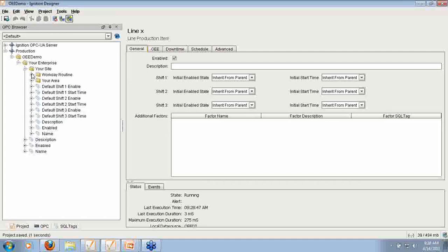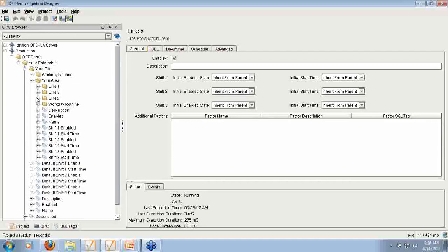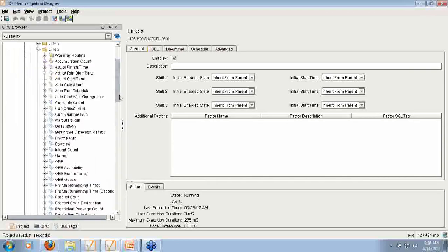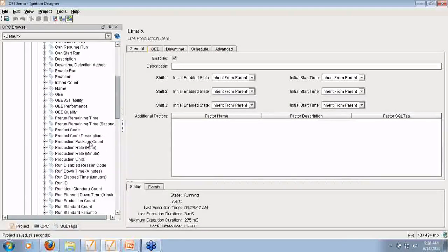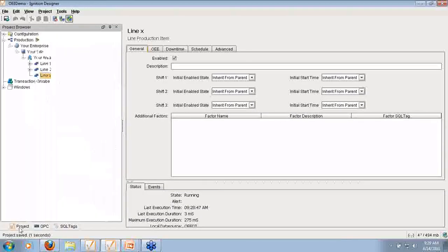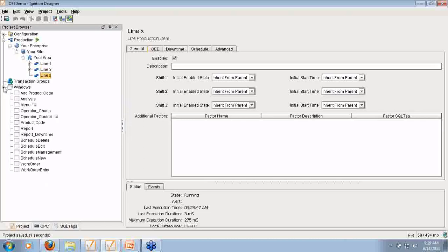Once that production line is in place, then a whole wealth of information is available. There's line X that I added. So now we can start getting production rates by hour, our OEE values, and so on and so forth. So very much this supports maintenance of your system, because processes are going to change in your facility more than likely over time, and also your requirements of screens and production and stuff like that, the information you want to get out of the system.